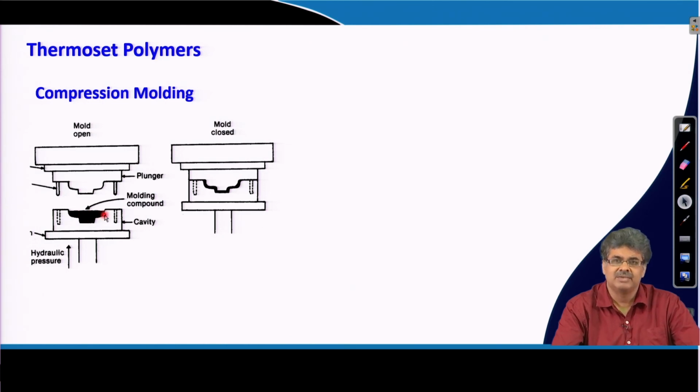Once it becomes soft, a mold is compressed onto this molten polymer, and then it is allowed to cool. Hence, this product will form the shape of the mold as shown here, and once it is cooled, you can take it out by an ejecting process.